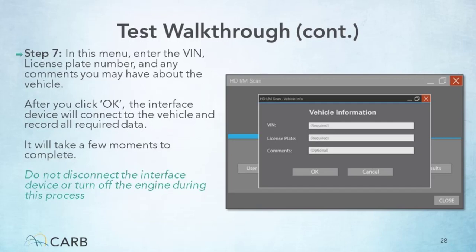The Vehicle Identification Number, or VIN, must manually be entered by the tester before performing a Clean Truck Check emissions test. VIN errors may result in delays in obtaining vehicle compliance. Therefore, checking the accuracy of the VIN is an important step when performing Clean Truck Check emissions tests. The most common mistakes are missing or incorrect characters. For example, entering the number 0 versus the letters O or D, the number 8 versus the letter B, or the number 1 versus the letter L.